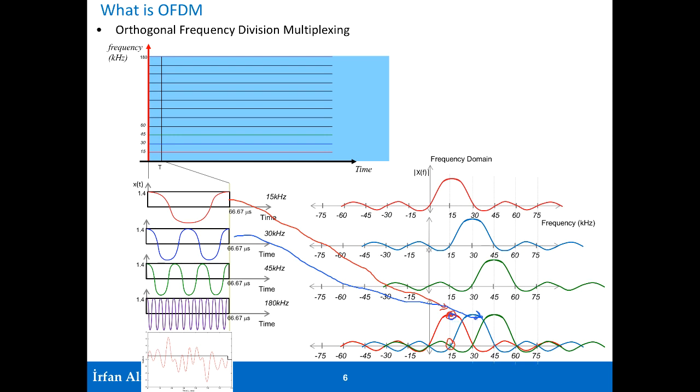So in the frequency domain, it becomes a lot easier to find out that these signals are actually orthogonal to each other, and I can put information into each one of these and they will not interfere, and I can decode it at the end very easily, because the other frequency components have zero contribution at the peak when a particular component is at its peak.